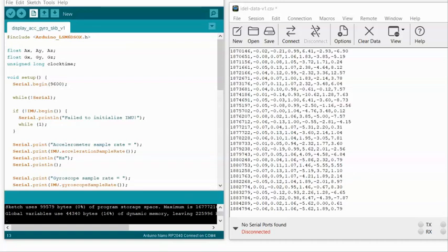In order for us to collect the data from the car engine, first we will run a simple Arduino code. This code will enable us to collect the data from the accelerometer and the gyroscope onboard the Arduino Nano Connect. We will also be using a third-party software, CoolTerm, which will convert our data using the serial communication straight away to an Excel file.